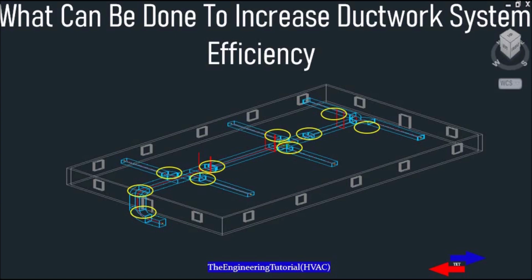And the T-section at the end of the main duct causes the air to suddenly divide and change direction, so there is a high amount of backflow here, which can again increase the static pressure and reduce the amount of air delivery. And the high velocity in the main duct, which is caused by the sharp turns and sudden bends, reduces the airflow into the branches on the left and right side of the system.